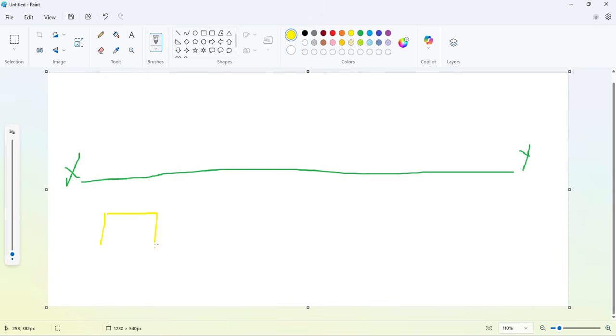While resting on HP, this is ABCD, and this is going to be the front view. This is our front view, and this is the top view. Naming A, B, C, D. So this is our resting edge, and this point will represent this side AB. So A dash, B dash.